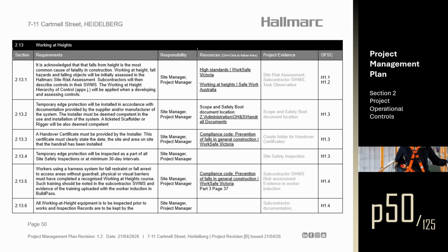Section 2.13.2. Temporary edge protection will be installed in accordance with documentation provided by the supplier and/or manufacturer of the system. The installer must be deemed competent in the use and installation of the system. A ticketed scaffolder or rigger will also be deemed competent.